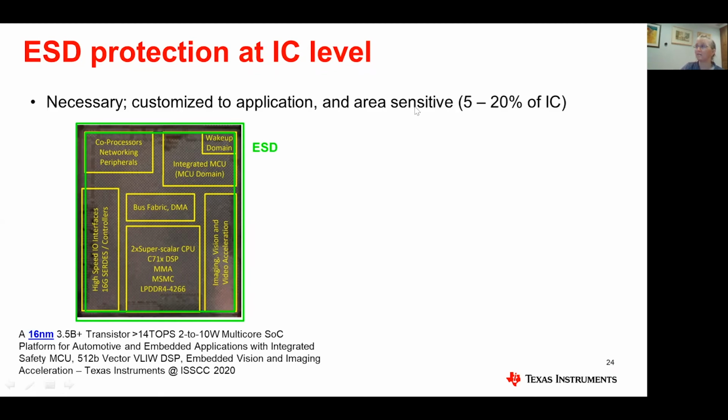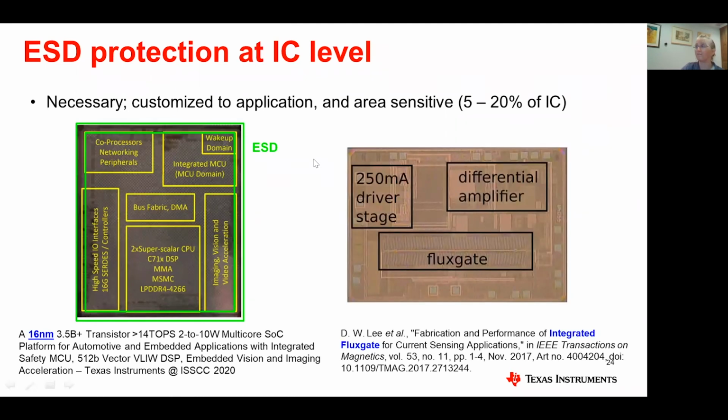In an average IC, the ESD protection can be anything from 5% to 20% of the IC real estate. So this is a highly integrated digital 16 nanometer design.